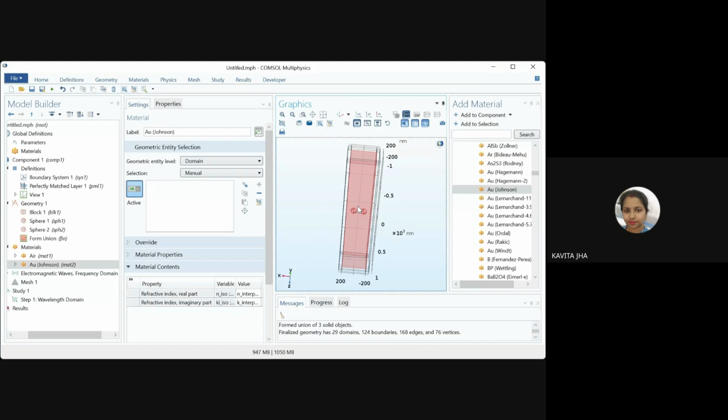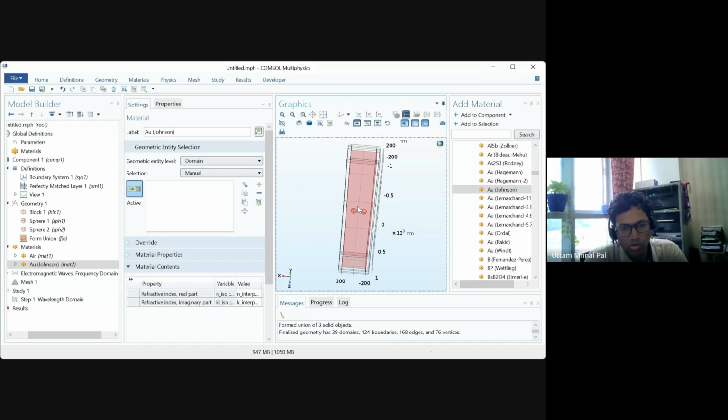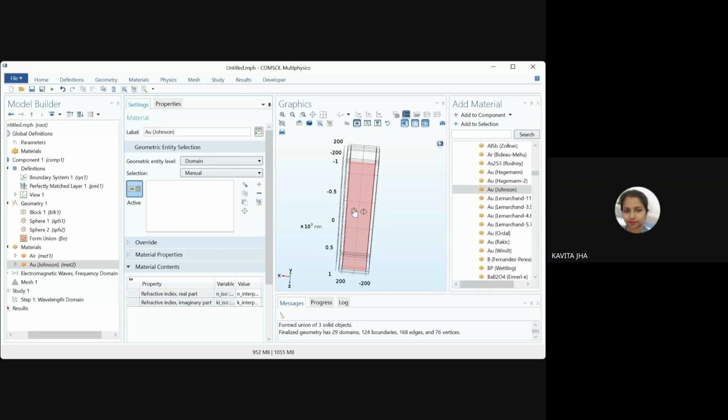Now what should I do, sir? Yeah. So the tip of the mouse cursor should actually overlap with the circle. Now the tip of the mouse is not overlapping. Now it's overlapping. But again domain number 11 is selected. You again use the broom to remove that domain. Then point the tip of the cursor. Do you have a mouse? No, sir, keyboard. Yes, keyboard, sir.